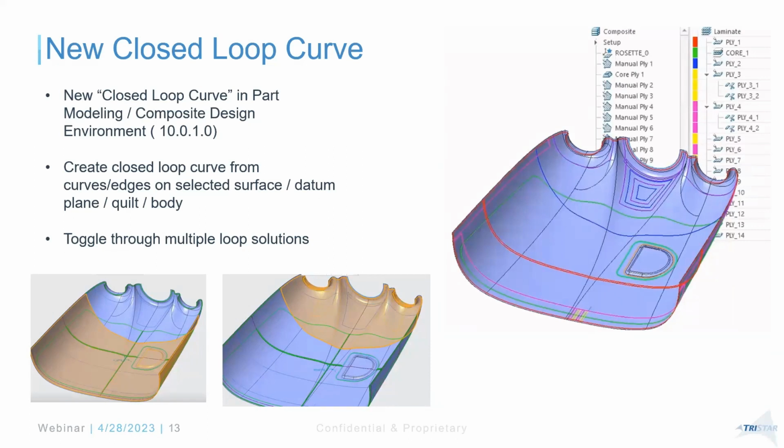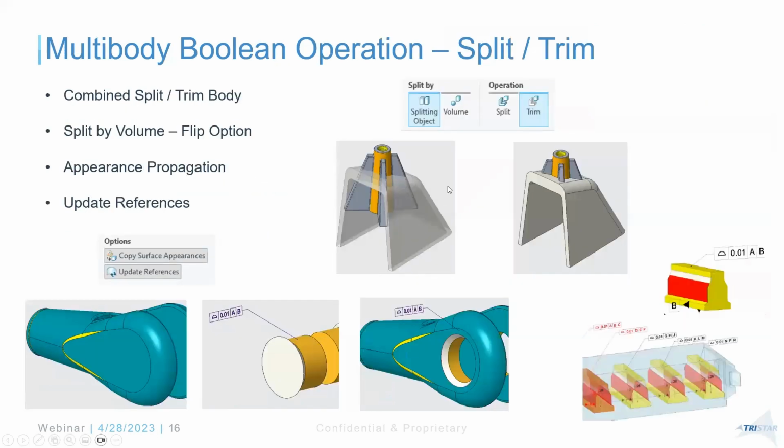It's almost like you're manually placing plies, giving angles and material properties and thicknesses, doing analysis work, etc., and also creating the flattened geometry. So that's where this could benefit, but it also works on a flat surface. It's available both in the regular part modeling, sheet metal environment, and in the composite design environment that'll be coming up in the next date code, actually. So that's where we could be using this technique.